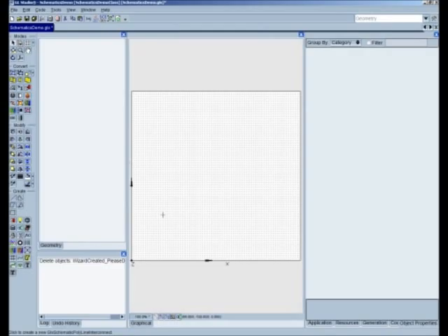The Polyline Interconnect tool allows us to create pretty much a set of tubes, similar to the way the polyline works. Just as a refresher, in order to use a polyline, we would first click once to establish our starting point. So I'll set it right here towards the middle of the screen. At that point, we get our line. We can go ahead and click and set vertices for our specific object.